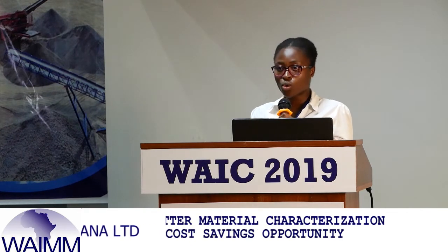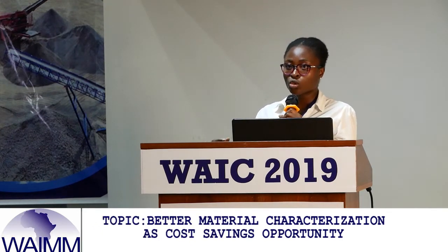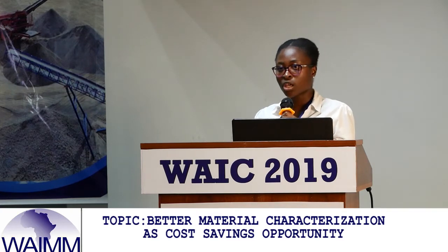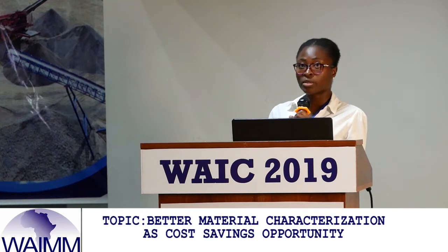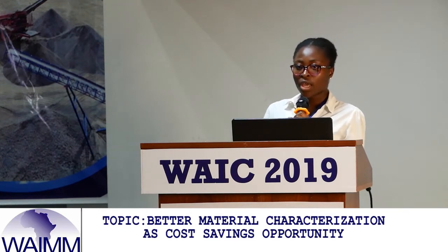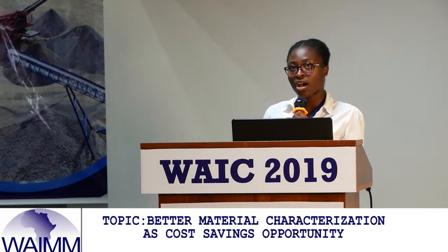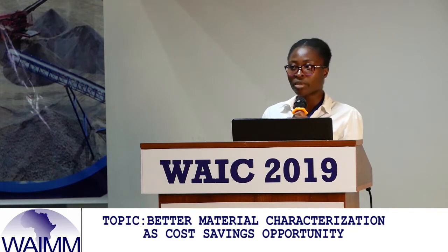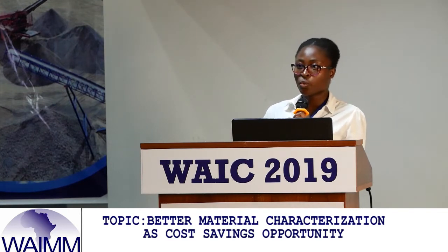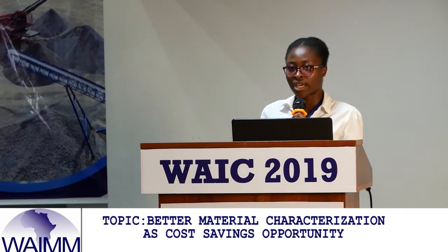When we do better material characterization, we can see that your material is actually stronger than what we might assume. If we did a site investigation and we did maybe 10 boreholes and we're able to get good cores to do triaxial tests, we'll have actual strength parameters to work with. When we don't have a good enough budget to do a good site investigation, we have to settle for what we call conservative estimates. That means that we are covering our bases. We don't want anybody to come and say in 5 years' time that Knight Piesold did this design and now we are seeing failures.